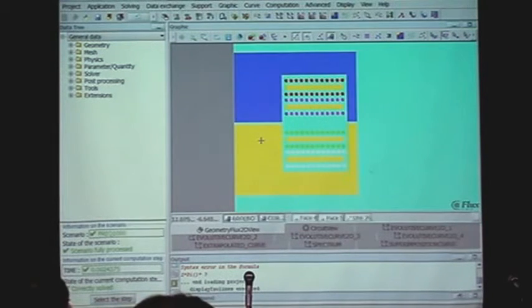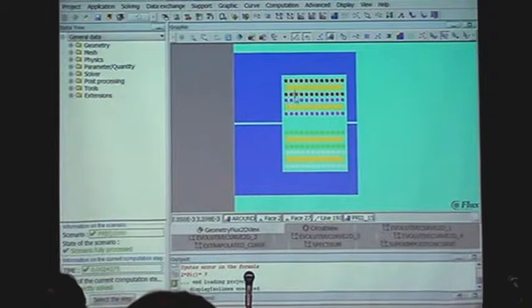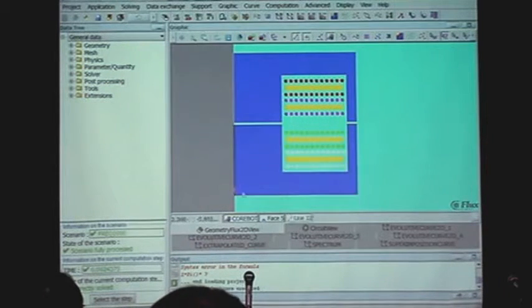We have a core here. We can adjust the air gap in it because that is going to help me play on the inductance of the coil and things like this. We have a primary. The primary is made of those many turns here. And we have a secondary, which is a big sheet of aluminum. Okay, and here we have two phases, so we can get one or the other in this case.